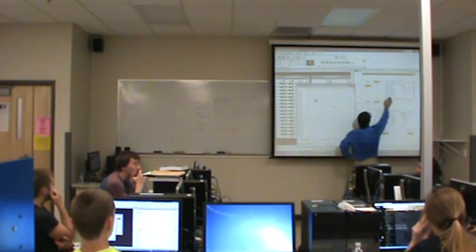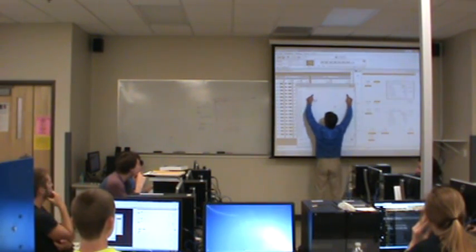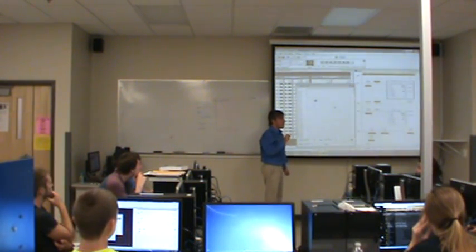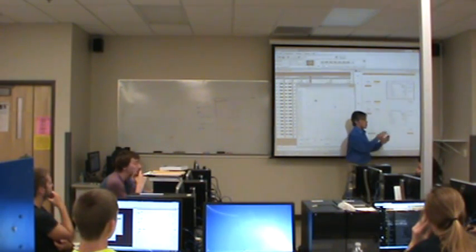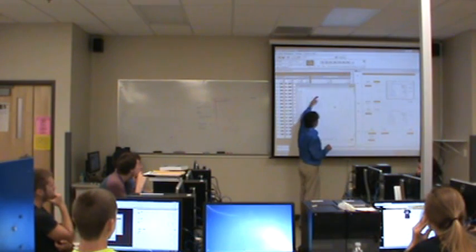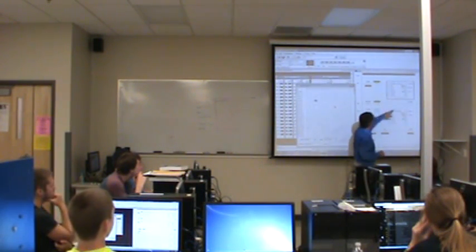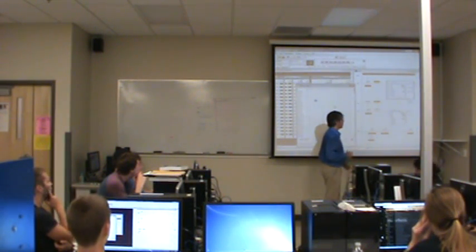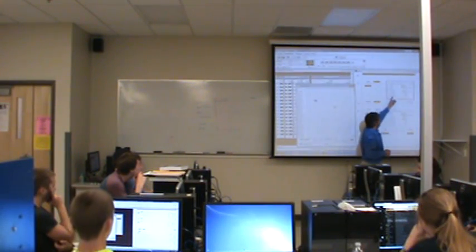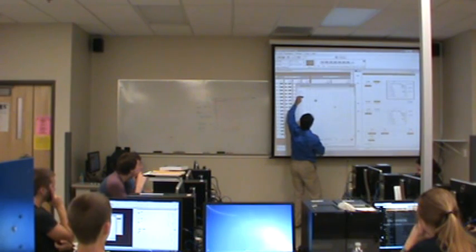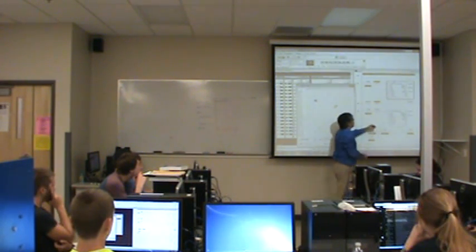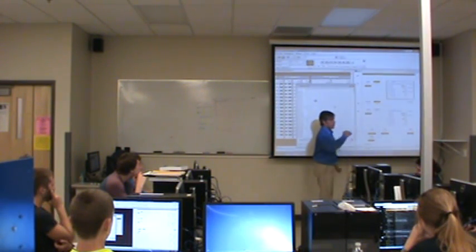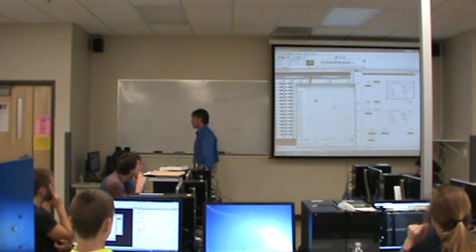But basically, this instruction is going to look at input 5, and it's going to constantly be looking for what's at address 1. It's going to look for that pattern. Until it sees that pattern, it will not trigger sequence output to change to the next step. But once it finds the pattern, then it'll find to be true for one cycle. It will cause the sequence output to go to the next step and set the outputs according to whatever's next in memory. And then this instruction will immediately go to the next line. It'll load this and start waiting for input 5 to match that line, because that's the next line in the list. So let me demonstrate it, and we'll see how it works.